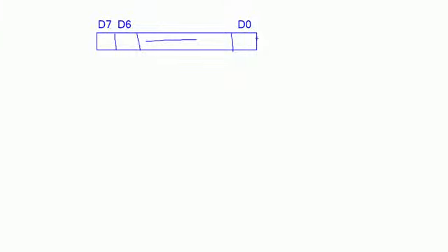Whatever the bit positions we are having now, I told you that static RAM is designed using flip-flops, and dynamic RAM is designed using capacitors, right? How many bits are there in each memory location? 8-bit information. Each memory location is able to hold 8-bit information. Now I'm just taking only one memory location, which is holding the 8-bit information. Each bit is called a cell.